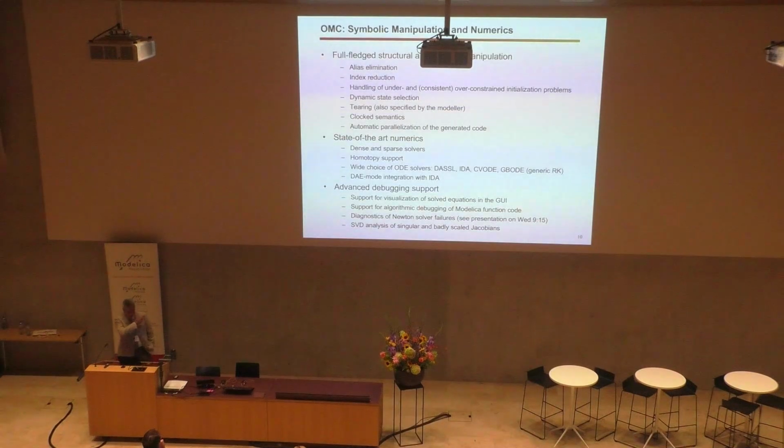Most importantly, this is a part that I'm very proud of. We try to provide advanced debugging support. I'll show you a small example in a minute. We have support for visualization of solved equations in the GUI, support for algorithmic debugging of Modelica functions, and recent additions: diagnostics of Newton solver failures. There will be a presentation on Wednesday morning if you're interested. And last but not least, SVD analysis of singular and badly scaled Jacobians. This is still a bit experimental, so next conference I hope I will be able to actually show some nice demo about that.